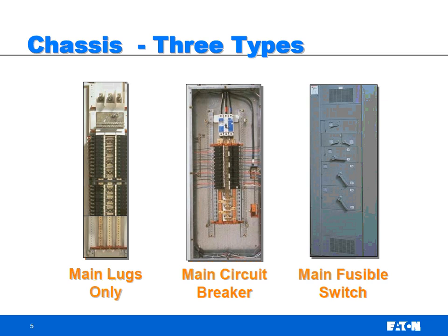So on a 100 amp breaker, if you throw a dart into the middle, say 35K, you probably are looking at a difference between, if you had a 1200 amp panel versus a 700 amp panel, $400 or $500 difference between main breaker and main lug. And if you don't need it for protection, then it's really a redundant, easy access to turn a panel board on and off.